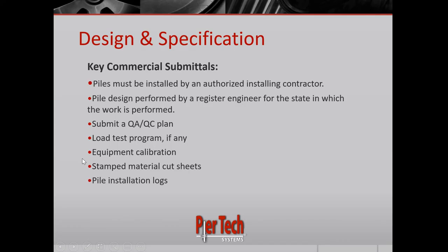And then we've got pile installation logs. So we showed an example of a pile installation log earlier. They'll want that log example in your submittal. And then for closeout submittals, you'll have to supply these pile installation logs for every pier that you put in on the job. This could be done the day that you do it or at the end of the project, depending on what the specifications require.